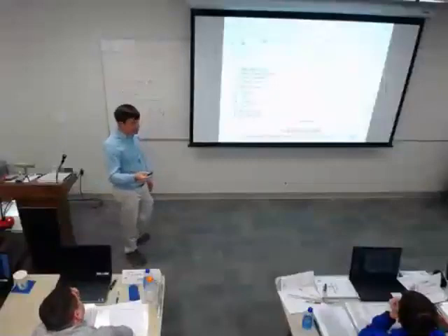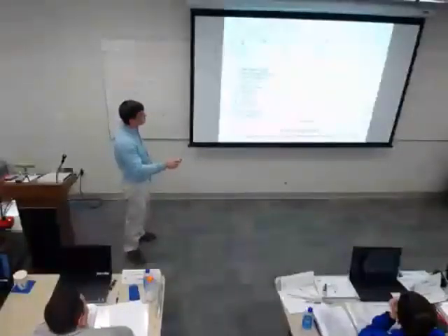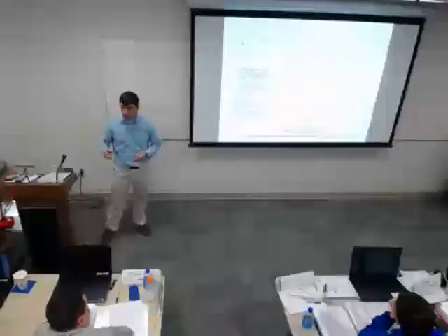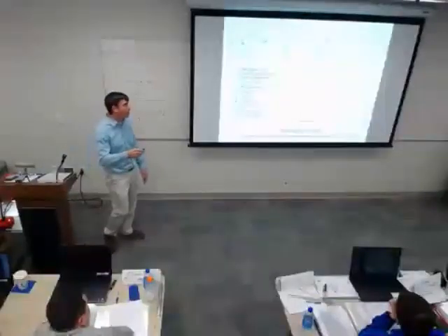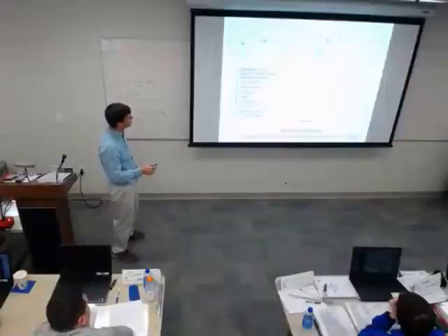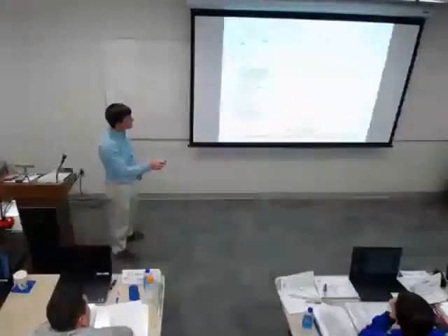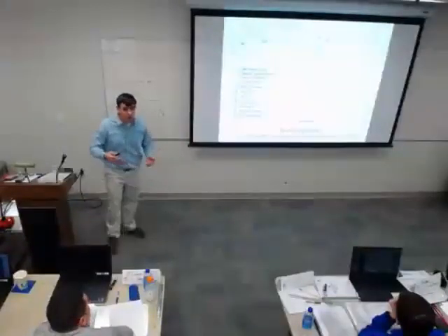Where would I take those readings? Well, we already talked about one. We're definitely going to take it across the fan. Our spec says you have to do a static pressure profile. It says to take pressures in a lot of different places, but places that would definitely be important potentially are across dampers, across the filter, and across my coils, and all those numbers might benefit me.